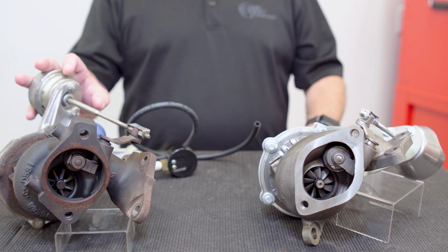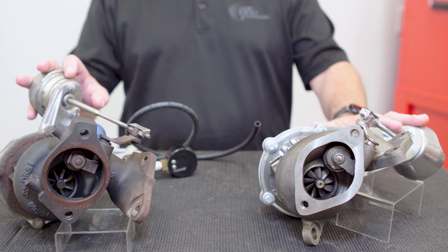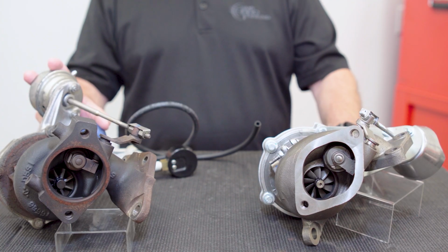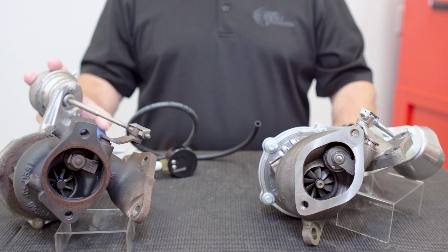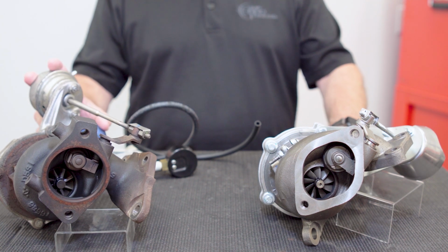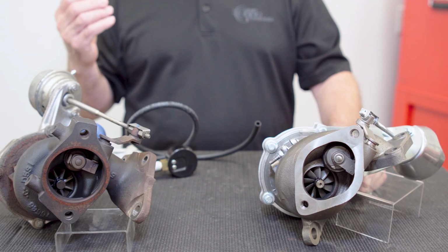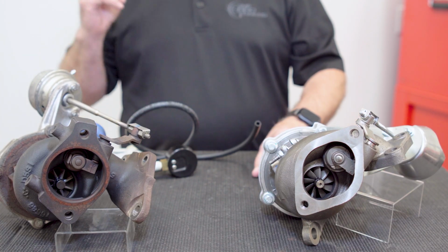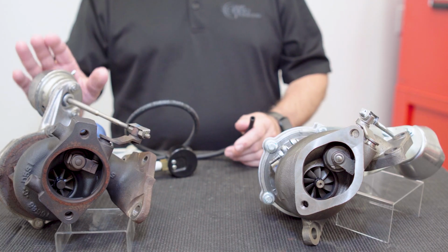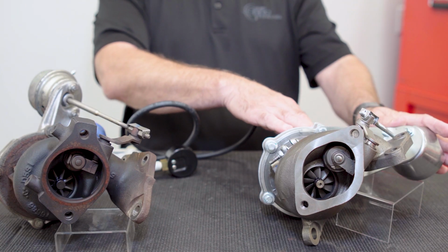Well, we have a vacuum actuated turbocharger here and we have a pressure actuated turbocharger here. And if you'll notice, on both of these, the wastegate is closed. What that means is when the engine's running, you have boost, period. If you don't want boost, then something has to step in to remove that boost. How does that happen? On a vacuum actuated wastegate, obviously we have to apply vacuum to it. On a pressure actuated wastegate, we have to apply pressure to the wastegate.